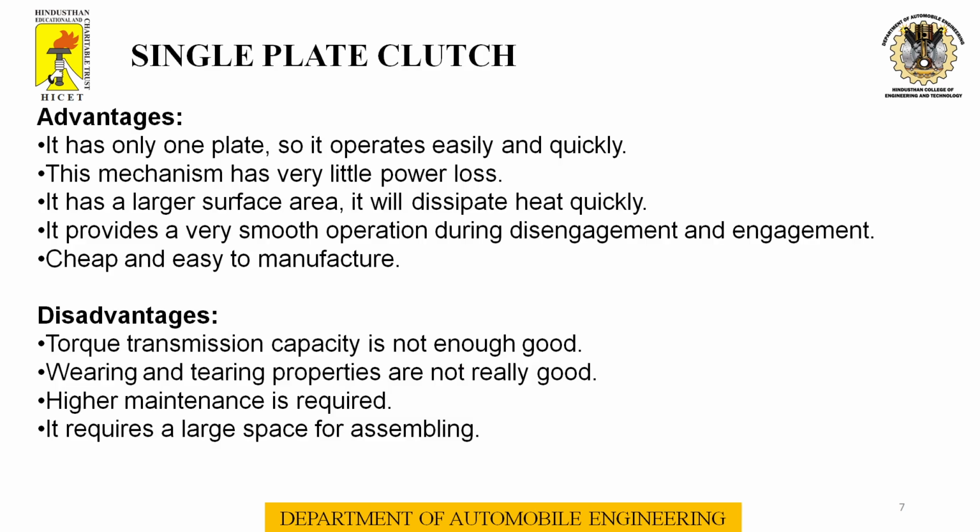These are some of the advantages and disadvantages listed over here. Advantages: it has only one plate, so it operates easily and quickly. This mechanism has very little power loss. It has a large surface area, so it will dissipate heat quickly. It provides a very smooth operation during disengagement and engagement. The last point: it is cheap and easy to manufacture.